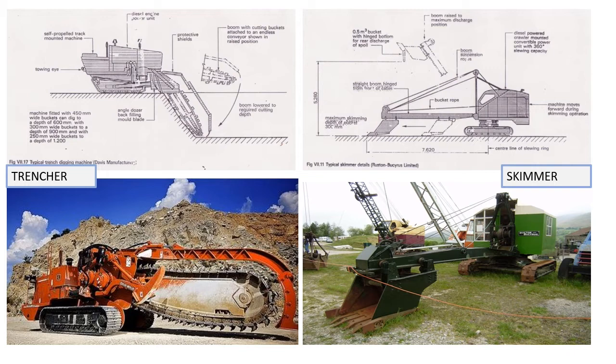Next is Skimmer. These excavators are rigged using universal power unit for surface stripping and shallow excavation works up to 300 mm deep where a high degree of accuracy is required. They usually require an attendant haulage vehicle to remove the spoil and need to be transported between sites on a low loader. Because of their limitation and the alternative machines available, they are seldom used today.